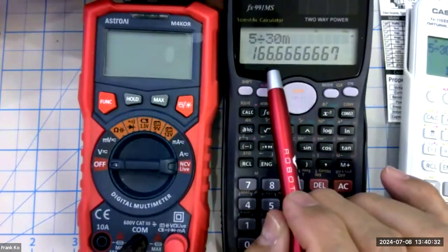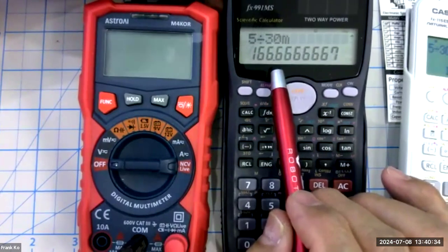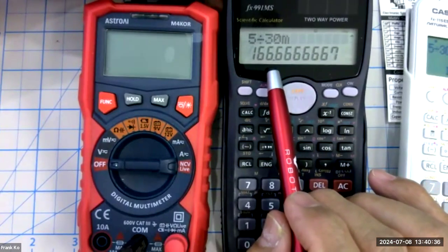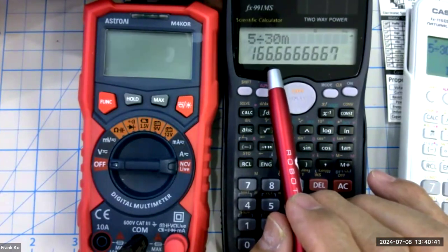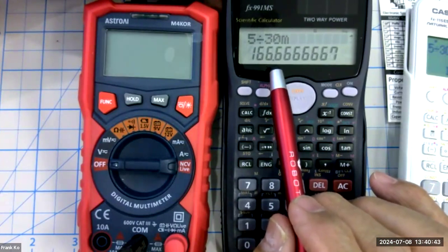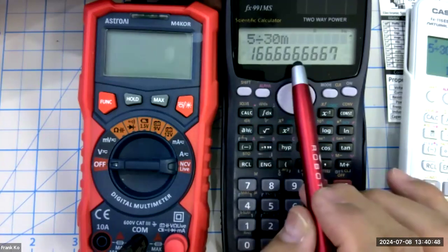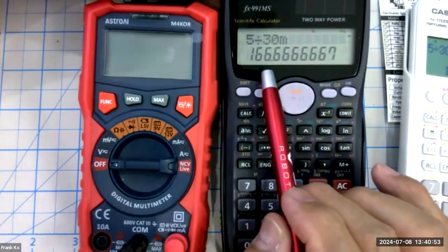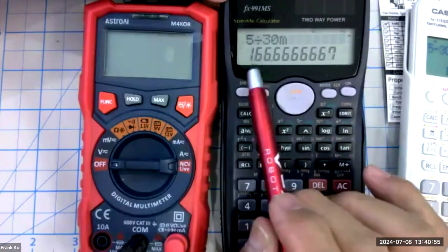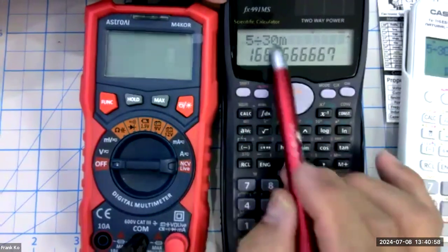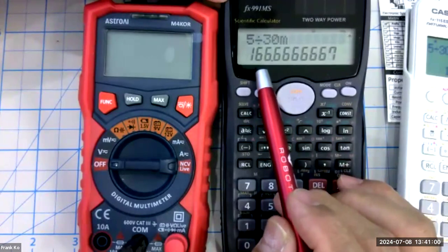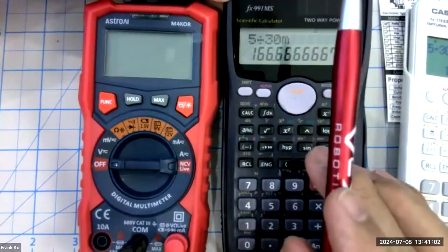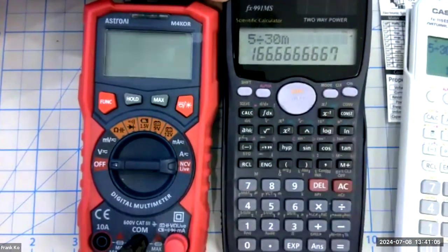All right, next, now that we have the ohms, how are you going to set up your resistances to get 166.67 ohms? Well, you've got 100 ohm resistors. You have less than 100, you have 10 ohm resistors. So I suppose you could put 100 plus six 10 ohm resistors or seven 10 ohm resistors, and you'll get close to 170 ohms. So with 170 ohms with a bunch of resistors in series, yes, you could achieve this amount of ohms in order to achieve the desired current of 30 milliamps.